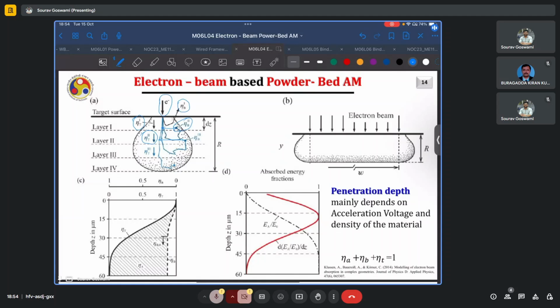And that is how we get this typical melt pool profile. For a wider electron beam, the corresponding profile is shown on the right, where you have this region of almost uniform melting, and then at the sides you have the characteristic bulge.